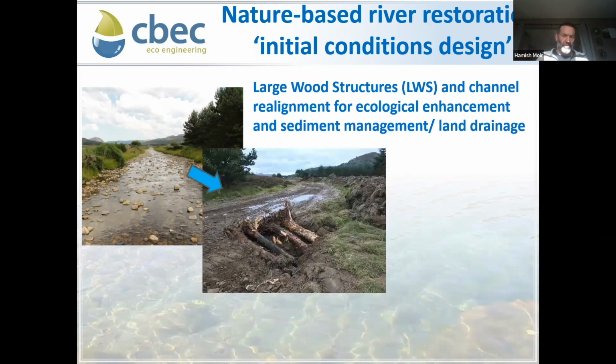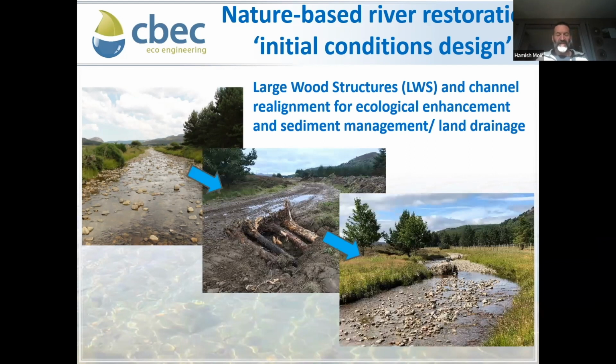This is the photograph I just showed of the channel as built. And this is it a couple of years after, and you can see the effect the large wood has had. The roughness of the large wood and the sinuosity of the channel has encouraged the deposition of these alternate gravel bar features. So the flow in this photograph is the same as the flow in this photograph, but you'll see much more physical diversity because of the asymmetry in the geometry of the channel.